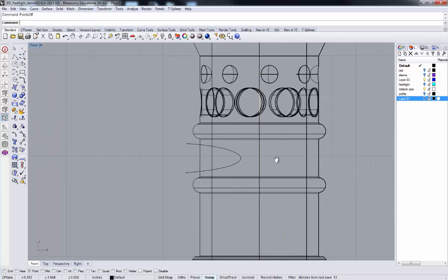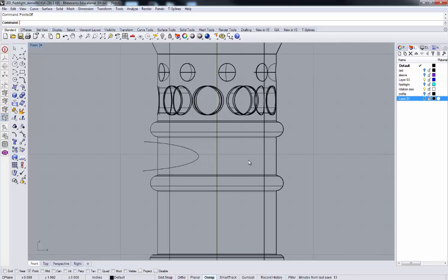And now what I want to do is duplicate this on each side. So I'm going to mirror this. Use my mirror command. And I'll use my near snap, so I'll get this axis near the center. Like that. And that mirrors with a copy on both sides. And so now what I'm going to do is use a command that's called project.